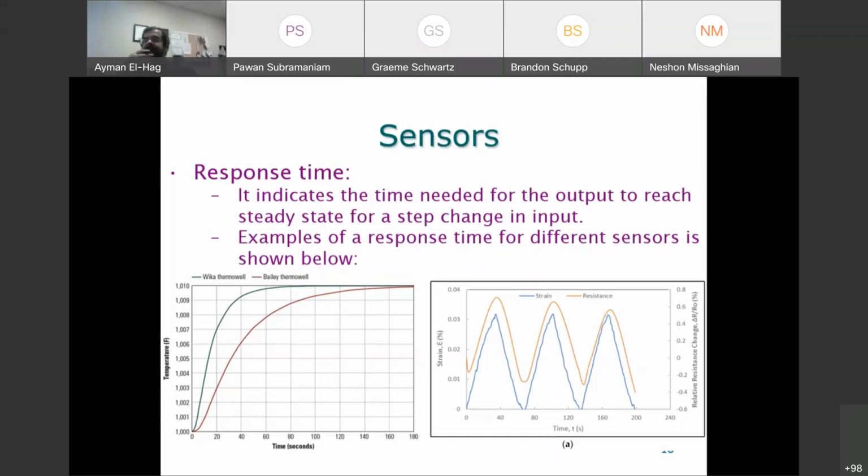Let's say, for example, you have a rocket. And in this rocket, the temperature changes in microseconds, and you need to know exactly the temperature at the sensor. Then you need an extremely fast sensor. But if you are measuring the temperature inside your room, using your thermostat, why would it have to respond very fast? You don't have to. It can take its time until it settles down.